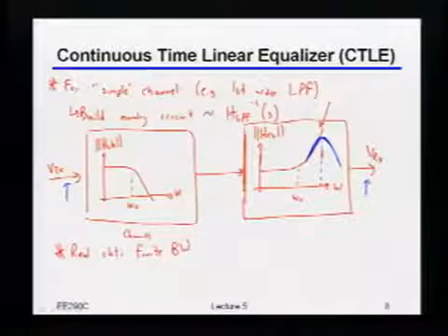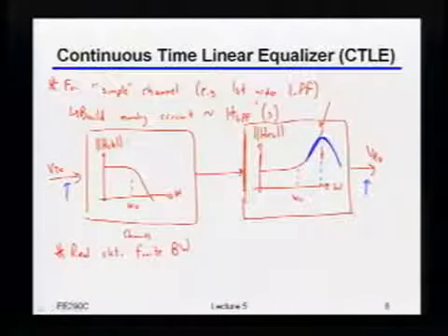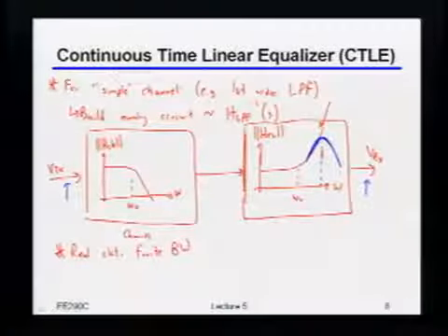Okay, so from the high-level standpoint, that's really all that's important in terms of continuous time linear equalizers. I'll just remind you briefly how you actually build them. Again, I'm hoping that most of you looked at this quite a bit in 240. If you don't remember, you can always go back and take a look at the videos there. But basically, typically you'll build this on the receiver. The reason for that is just that the impedances you're dealing with are higher at the receiver. So to get a certain voltage gain or signal swing, usually it takes you less power to do that versus at the transmitter.